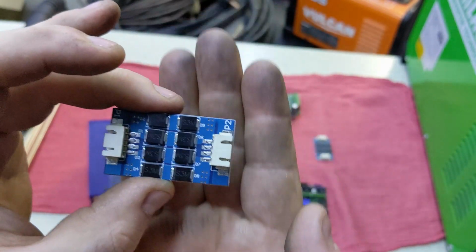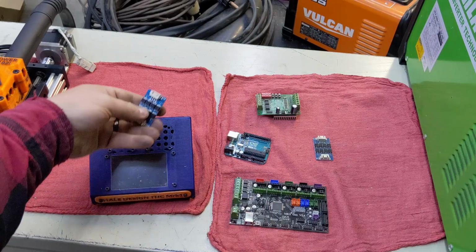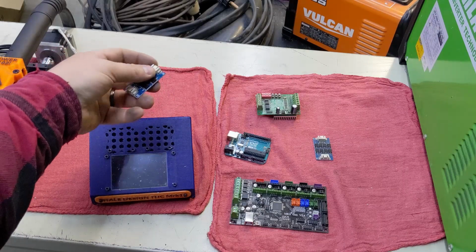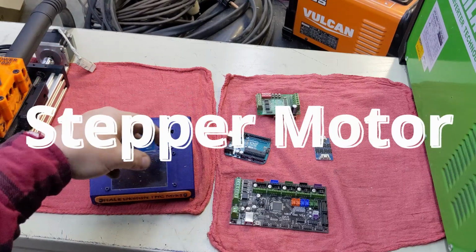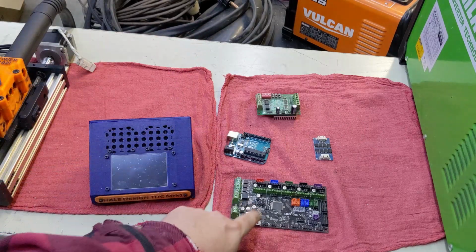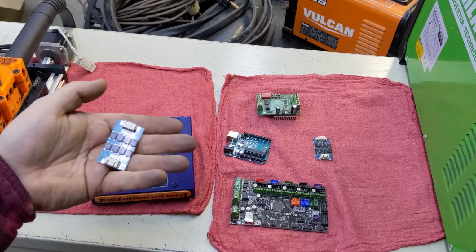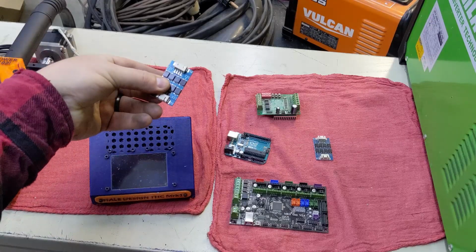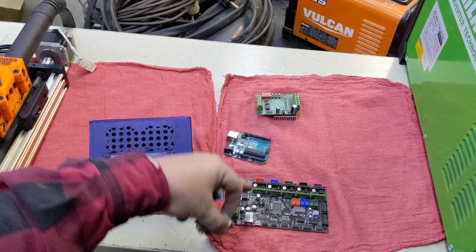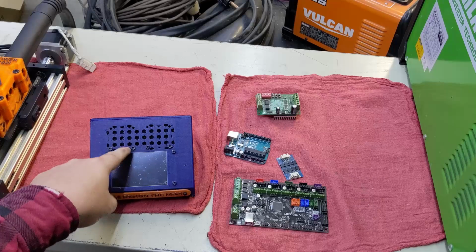But if you hook up one of these boards coming off of your torch height controller, hook it through this, and then into your connection to your stepper motor driver, you can only send signals one way to your motor, and signals from your main board won't go all the way around and go back into this guy, which is bad. You don't want that. This would stop it. You'll need two of these boards, however. One for your main board on your Z-axis, and then one for this guy.